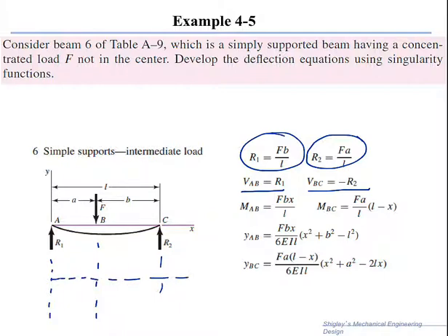would have a vertical value of R1 here, and then under the force F, I will have a change, that the change in the shear is the same as the magnitude of F, and then I would have minus R2, and this is plus R1. So this is the shear force diagram.